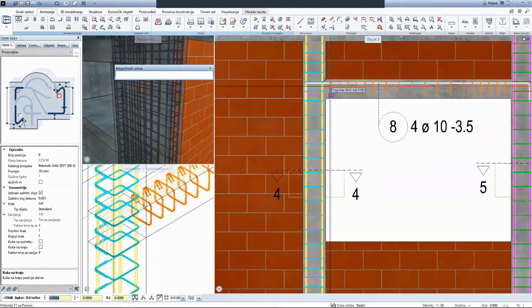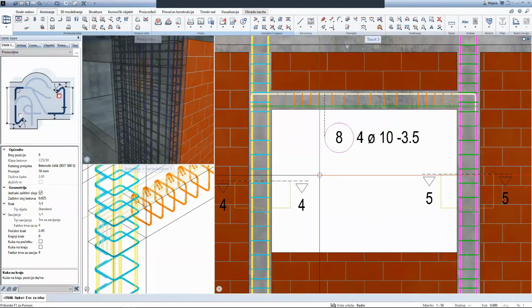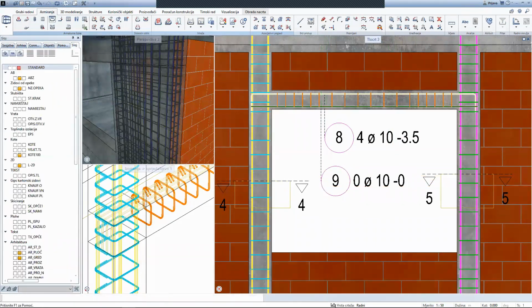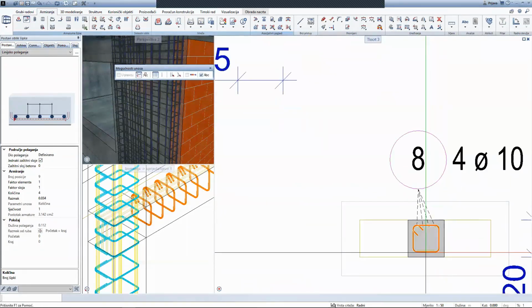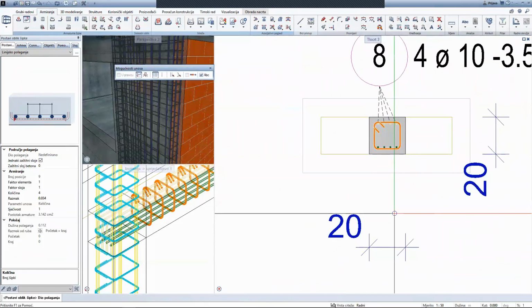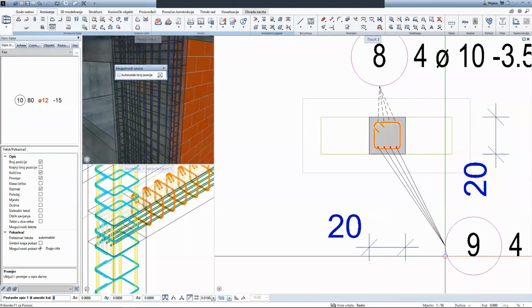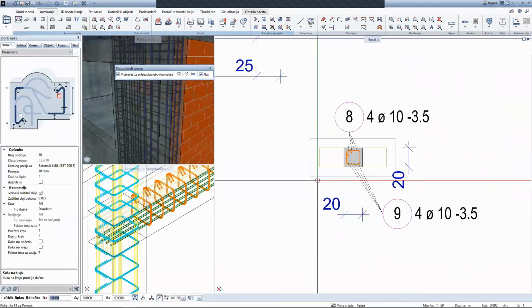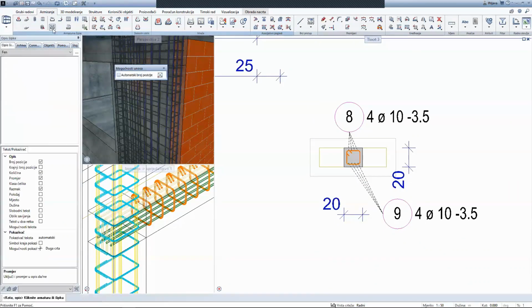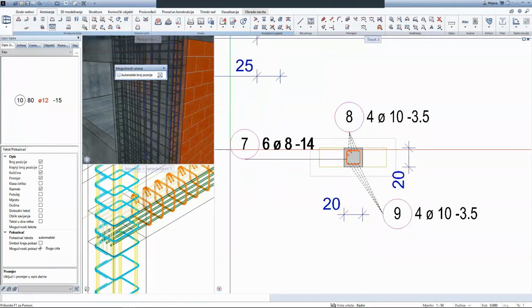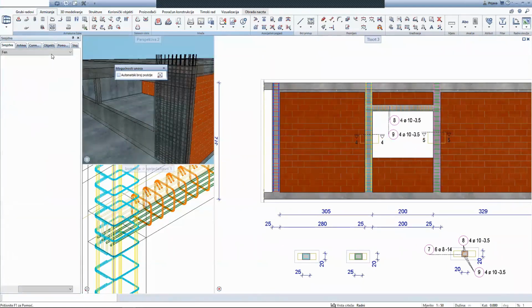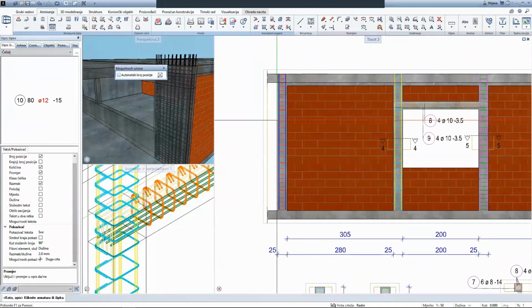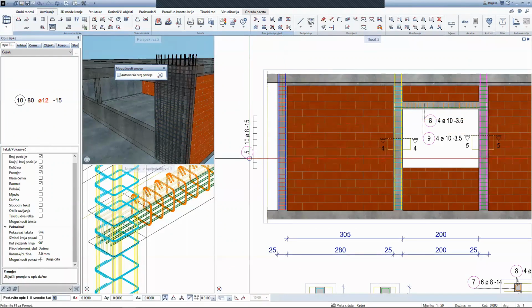You can see your reinforcement in 3D animation view so that you can always check the collisions between bars and easily fix any mistakes. Okay, so now when you place your reinforcement, this is the bottom area of the beam. And when you place all the bars, you can easily label all the bars. Of course, for labeling, there are a few types of labels.